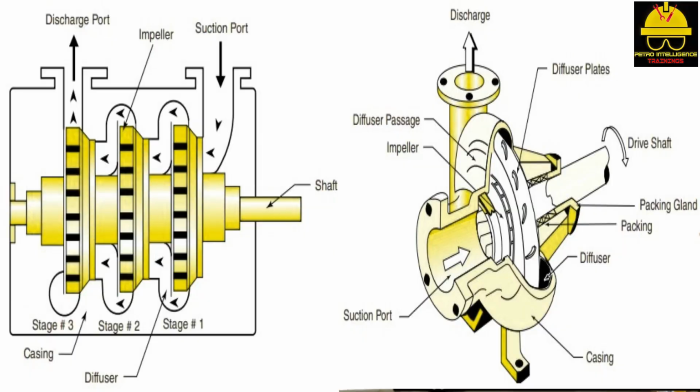as shown in picture. Centrifugal compressors have one moving element, the driveshaft and impeller. In a centrifugal compressor, the impeller discharges into a circular, narrow chamber called the diffuser. This narrow opening completely surrounds the impellers. As back pressure builds in the impeller, gas velocity is accelerated through the diffuser assembly and into a circular volute.